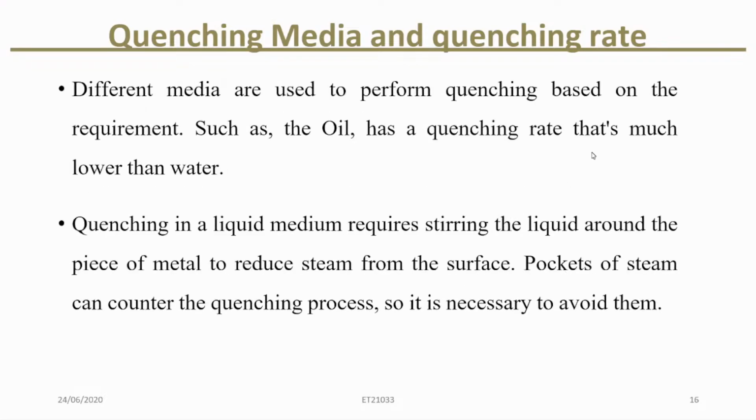So when we quench a hot part, we choose the liquid based on how fast we want to cool. Oil cools slower than water. That's useful when we want to reduce cracking or distortion. And water cools very fast, but it's harsher on the part.